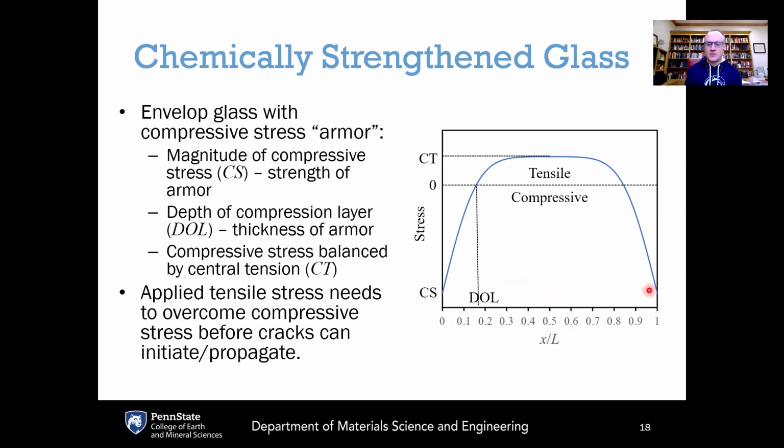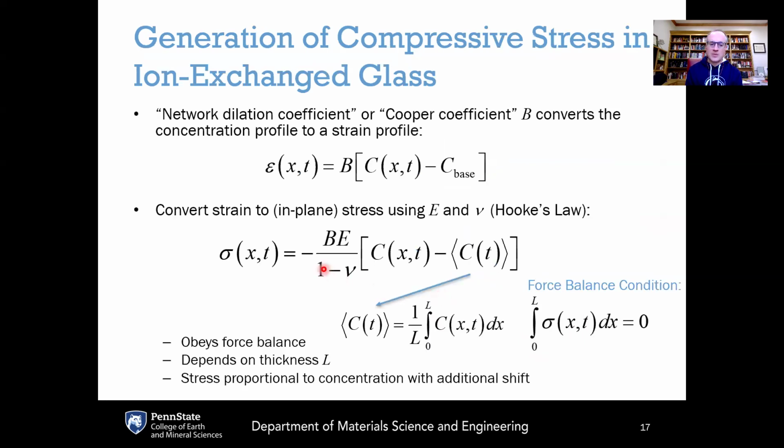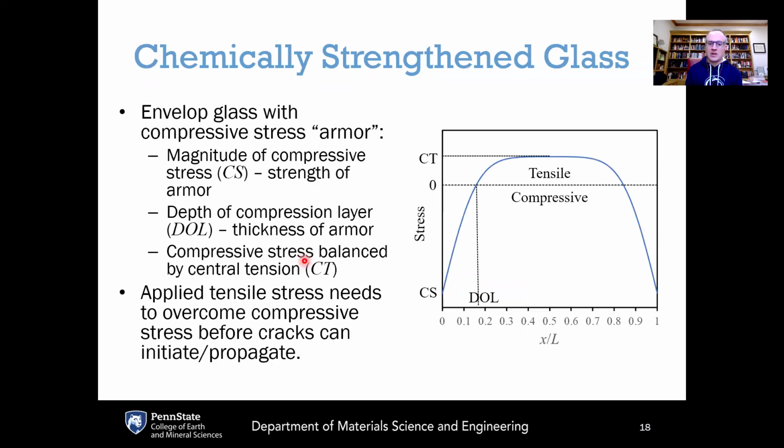At both surfaces, we've got our maximum of the negative stress. According to this sign convention, negative stress is a compressive stress. That comes from the minus sign out here. So this negative stress is a compressive stress, and that maximum of the compressive stress is occurring at these two surfaces of the glass.